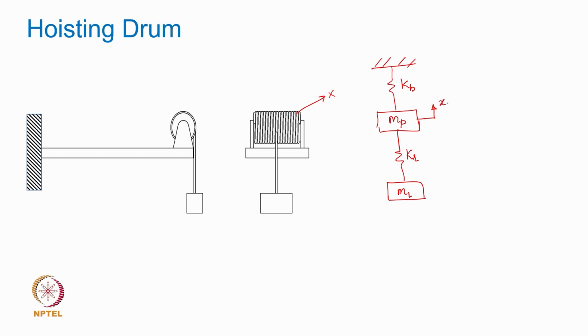And then I have 1 degree of freedom here, maybe x1(t), as the degree of freedom with which this end of the beam is going to move. And then I have another independent degree of freedom with which the load, if perturbed, will move. Because they are connected by this compliant element, they can move independently, they cannot be constrained to move together.